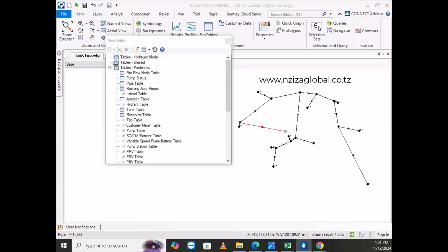But this is meter cubic. You supply 6.1 meter cubic per hour. Then you multiply by 24. You get per day. Yes. 6.1 times 24 gives 146.88, about 147 meter cubic per day.